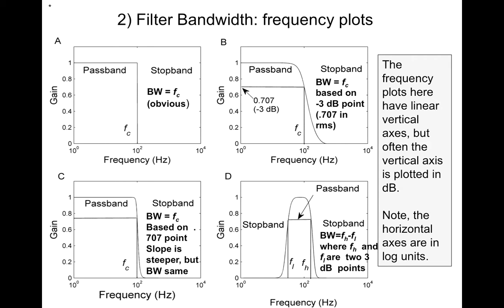If you have a system that looks like figure B, notice that some of your frequencies of interest will be attenuated or reduced a little bit by the physical filter itself. So it's going to distort your signal, because from where the knee of this curve begins to where our cutoff frequency is defined, you have a changing amplitude in the frequencies that are being passed.